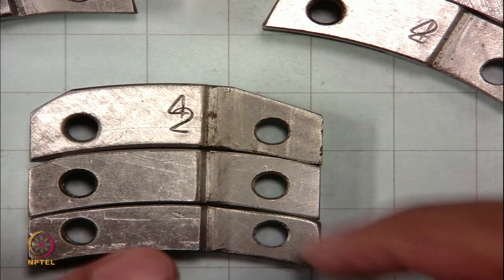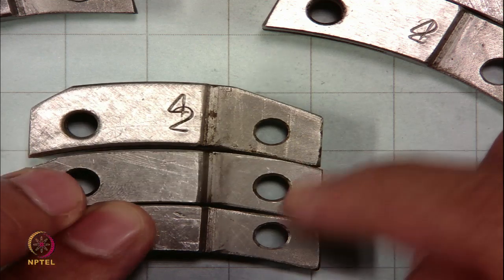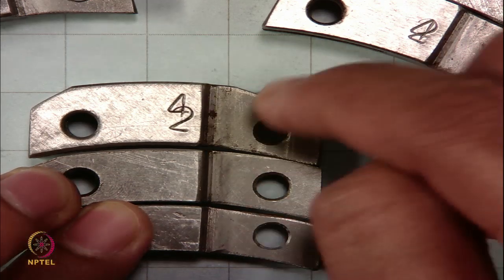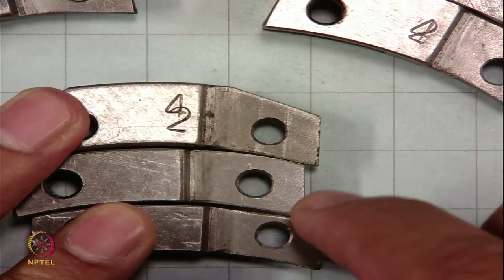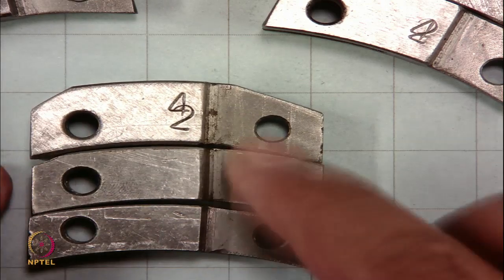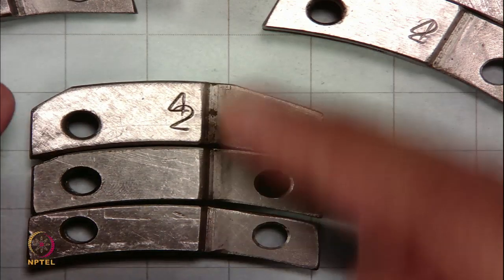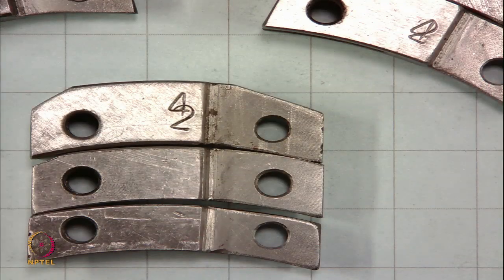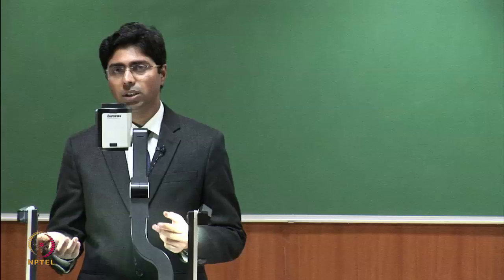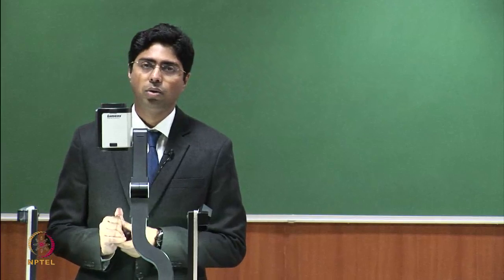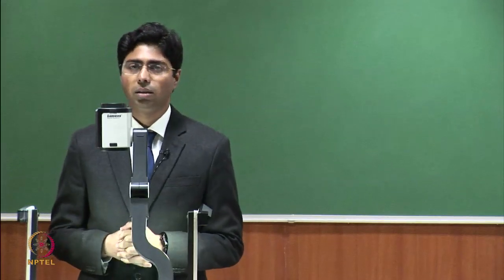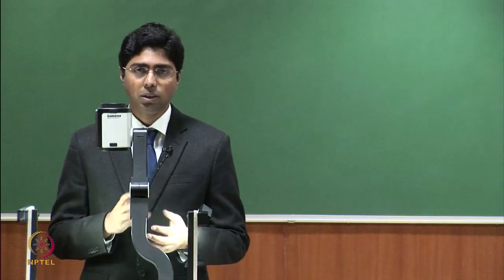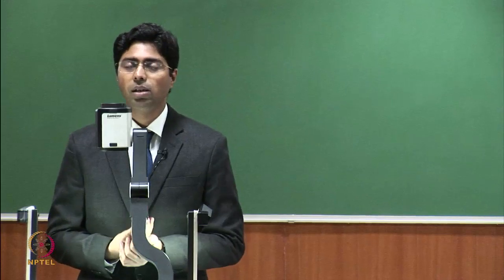So, when I am switching from this link to this, it means one pitch is possible, and when I am switching from this link to this link, 2 pitch is possible. This height is carefully designed and the profile has been created so that the required amount of pitch can be generated. In normal practice up to 3 pitch is possible. Usually we do not go more than 3 pitch, because then there is a high strain on the needles and needles may break, but usually 0 pitch is always available.